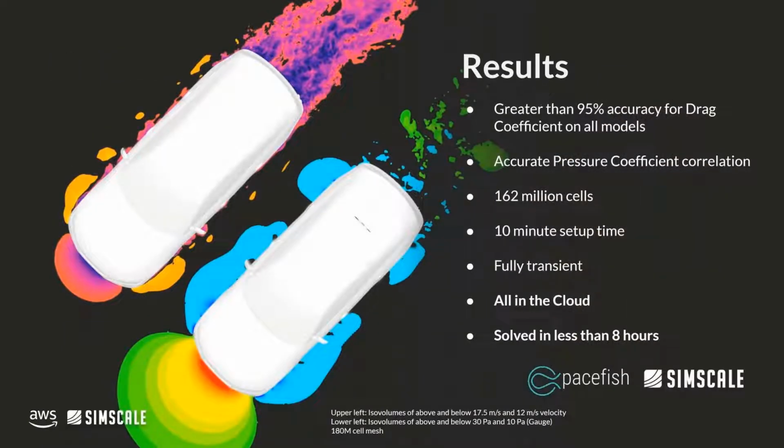Comparing against the original Drive AER experimental results published by Angelina Heft at the Technical University of Munich, reveals greater than 95% accuracy on drag coefficient for all models. For the largest, most complex model of over 162 million cells, the simulation time was under 8 hours for fully transient result, a snapshot of which can be seen on the left-hand side. This indicates an unseen-before turnaround time in the world of automotive aerodynamics, and could only be achieved by utilizing new workflows assisted by high-performance computing.